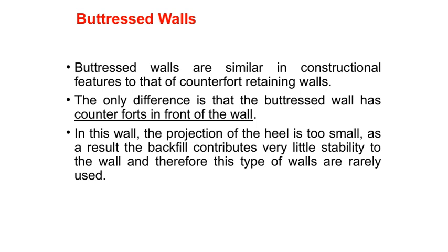However, one key aspect to keep in mind is that in buttressed walls, the projection of the heel, the part of the wall that extends beneath the backfill, is quite small. Because of this limited heel projection, the backfill contributes very little to the overall stability of the wall. This means that the wall itself needs to bear most of the load, which can be a limiting factor. As a result of this design characteristic, buttressed walls are rarely used in practice. Their limited ability to utilize backfill stability makes them less efficient compared to other types of retaining walls.